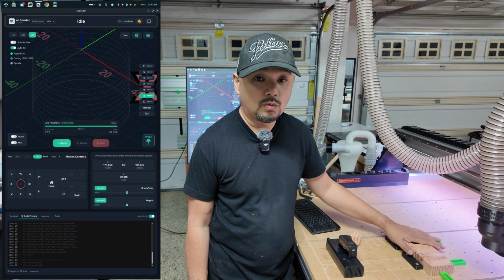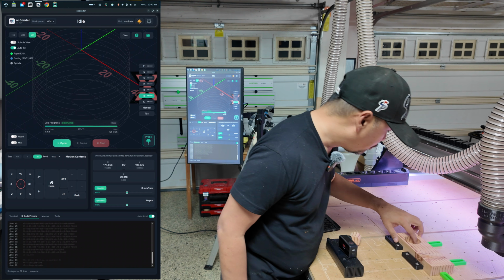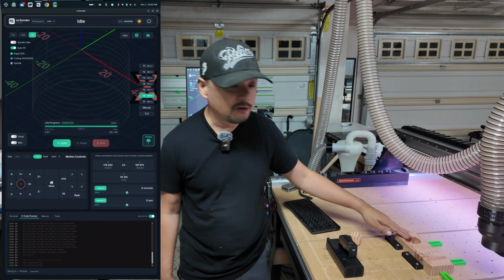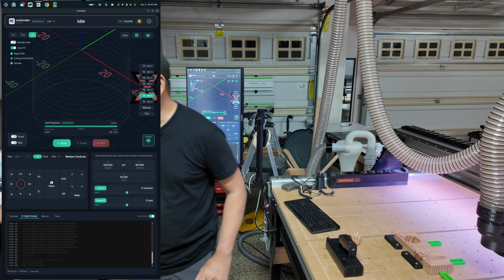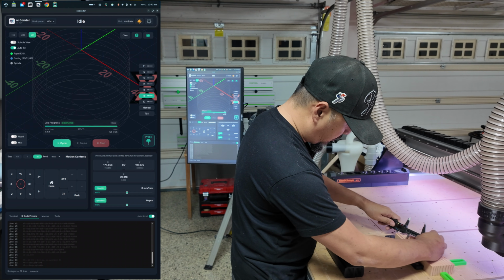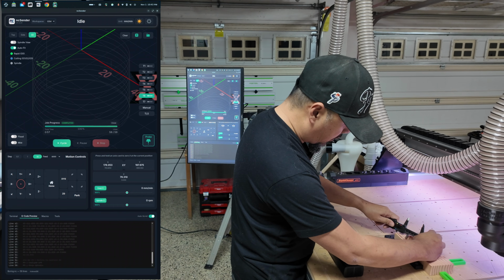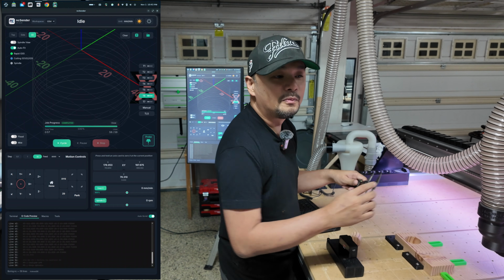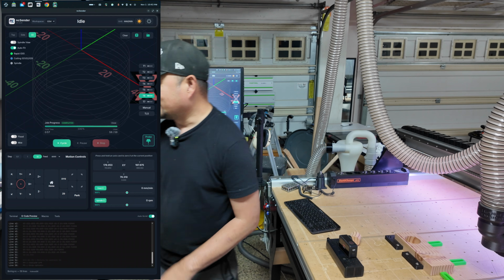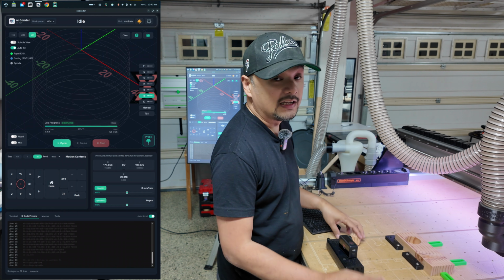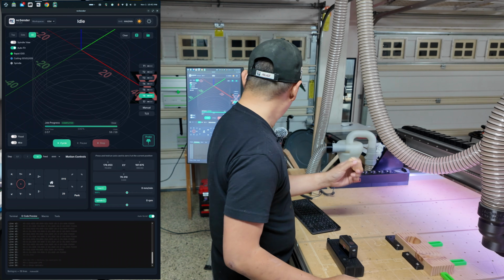That's 0.1 difference out of spec on my target, which I think is really good. Yeah, it's 49.95. So actually it's 0.05 out of target. 0.05 millimeter, not inch, that's a millimeter. Okay.